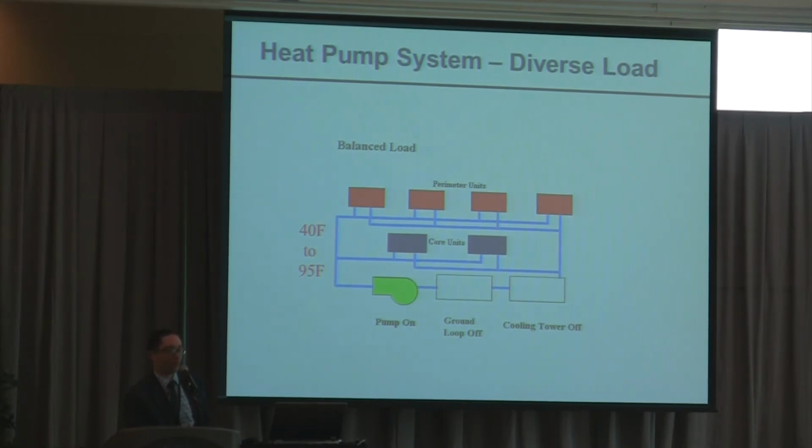The heating system is going to be combustion based, right? So you're burning something and sending waste heat out the stack. And simultaneously, your air conditioning is taking heat out of zones in a building and rejecting it to the outside air. What we're doing with this system, with a water loop and a pump, is recovering heat from the zones that are in cooling mode, the blue ones there, and delivering it to the zones that are in heating mode.